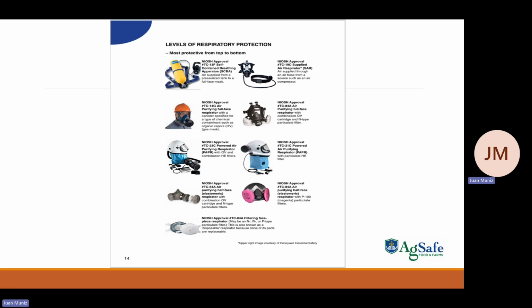So that is why that one over here offers a little more protection, because it's a combination of an organic carbon type filter along with a filtering media. All right, so that's why this one would be a little bit better. This one just has the high efficiency filters, and that one has the organic carbon filters along with the pre-filter.